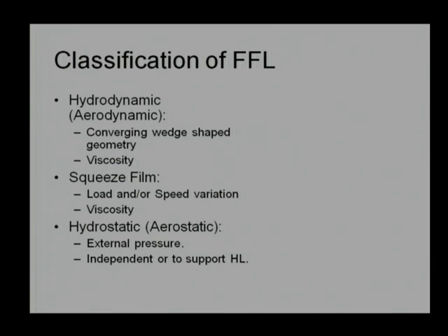The second mechanism is a squeeze film. This is basically governed by speed variation in the direction of film thickness, or changing the magnitude of the load or changing the direction of the load. There should be some sort of variation which brings squeeze film into action. This mechanism will be accounted for only when we have a load variation or speed variation. Viscosity also plays an important role in this kind of mechanism.